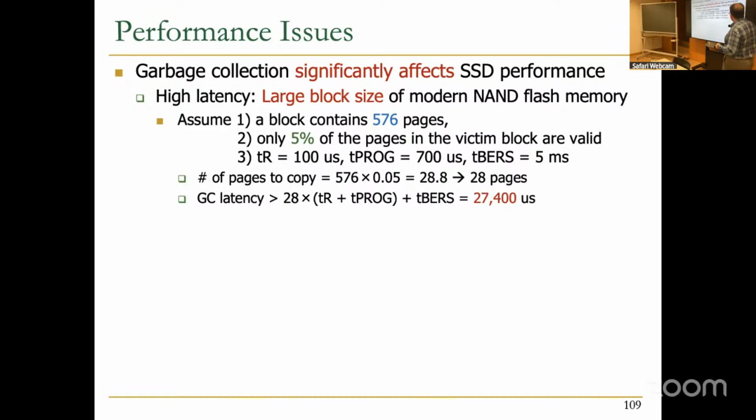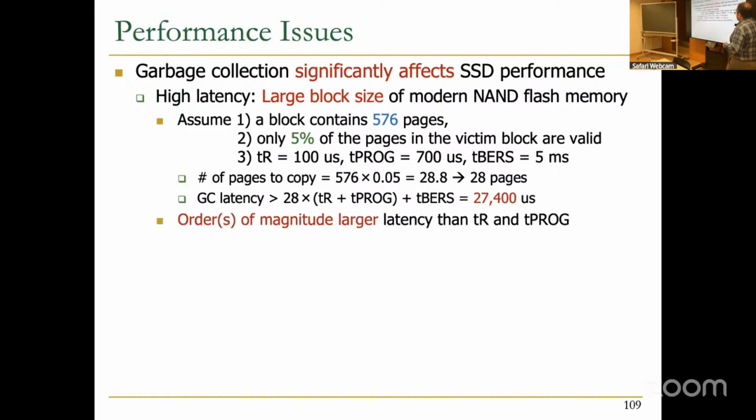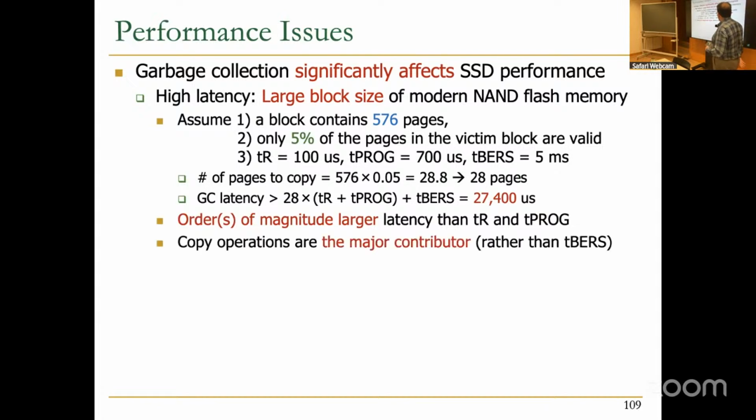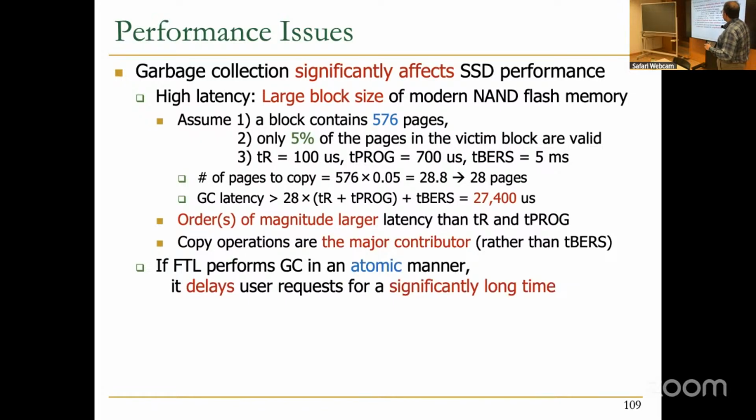And this is actually a lot, like 27 milliseconds, which is orders of magnitude larger latency than read and programming. So that's why garbage collection is so expensive. And if the FTL performs garbage collection in an atomic manner, it delays user requests for a significantly long time. That was the case in the past. When you were profiling your SSD, the performance was good, but at some point garbage collection starts and you were seeing a significant drop in your performance because of garbage collection.